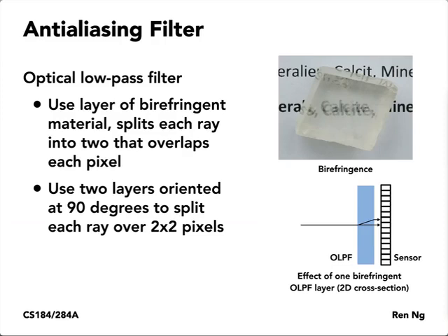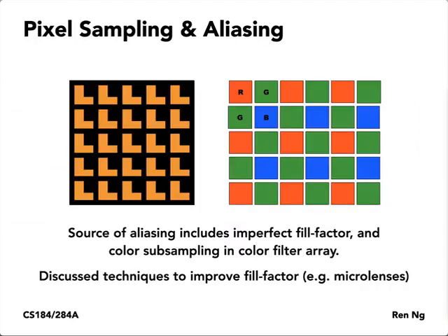And the way to interpret that is that now the filter that's incorporated is 2x2 times wider, where before we were integrating over the area of 1 pixel. That was the low pass filter that was available to us. Not enough. Now with the anti-aliasing filter here, it's doubled up. Okay, so we're integrating over a pixel area that's 2x2 as large. And because we're sampling in this color filter array in the worst case by a 2x2 subsampling, that's a good amount of high frequency knockout to match this subsampling pattern that's here.